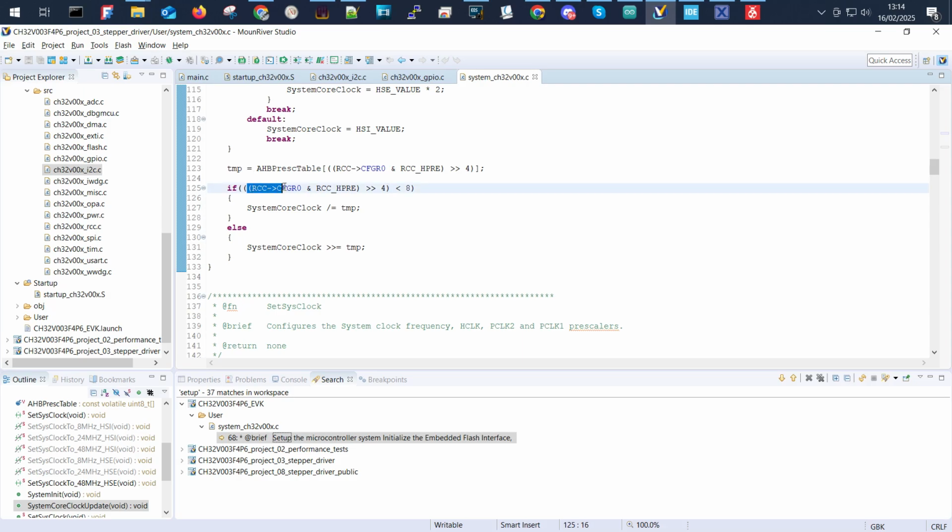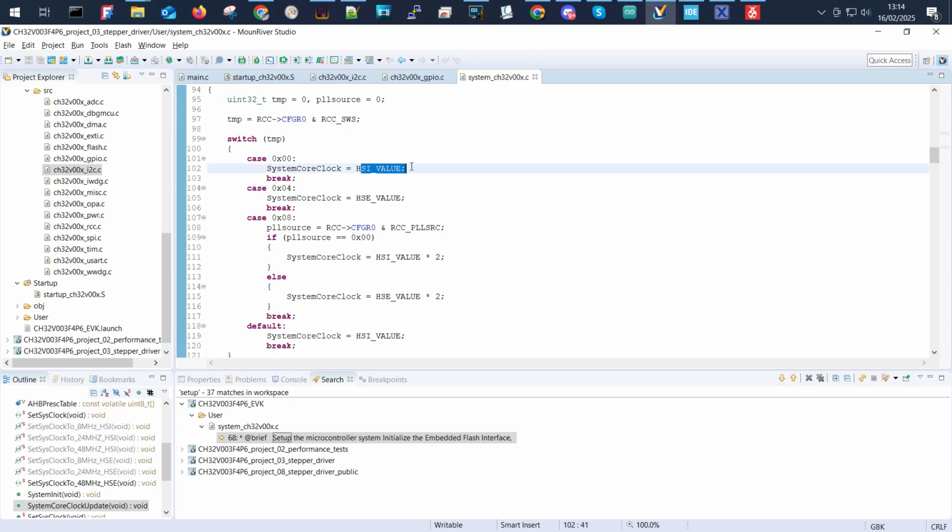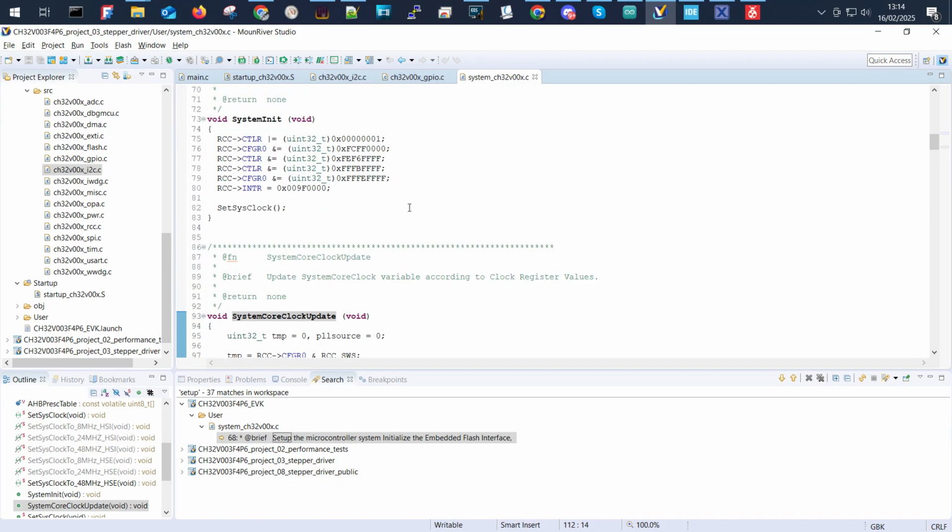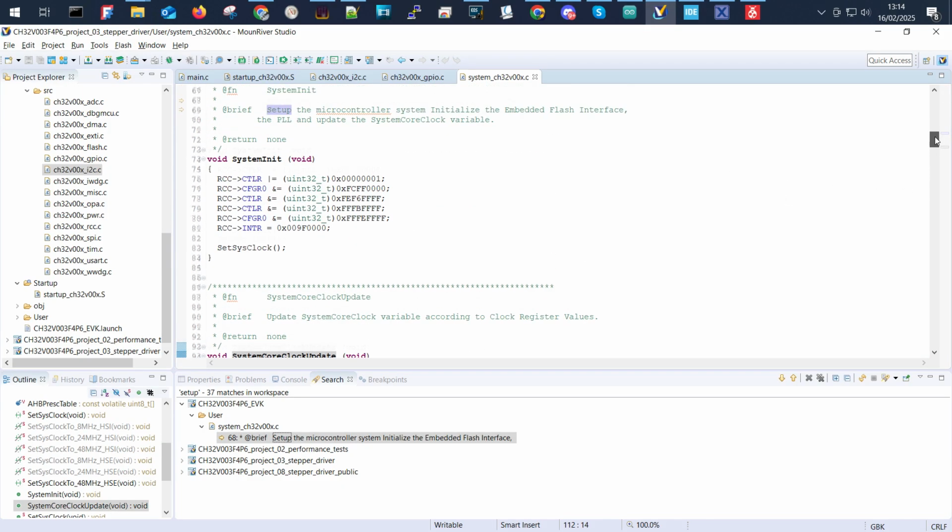We see already what needs to be done. We have indirection with the configuration registers, and we are setting up the hardware to use an internal oscillator, an external oscillator, a PLL, whatever needs to be programmed through the configuration headers.